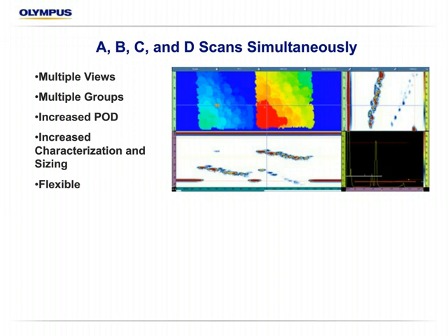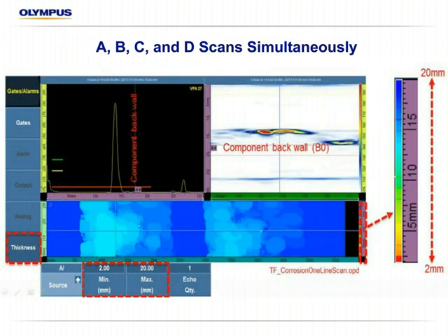So this is typically what we're looking at. We have the C-scan as our map, so we've either done a one-line scan in a straight line, or we maybe did an XY scan over a larger area. And we've defined the unit based on what type of thicknesses we are concerned with, nominal wall to some other level, and this palette is fully customizable to the application.